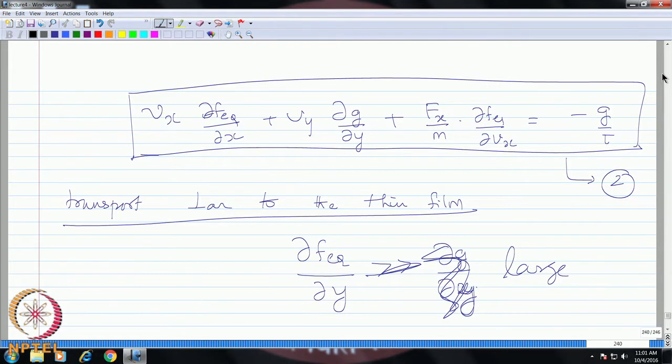This was attempted in 1993 by Professor Arun Majumdar. In this case, the distribution function is not explicitly used, but he defines a moment of the distribution function called the intensity. Based on this intensity, he solves the Boltzmann transport equation in terms of what he calls phonon radiative transport.